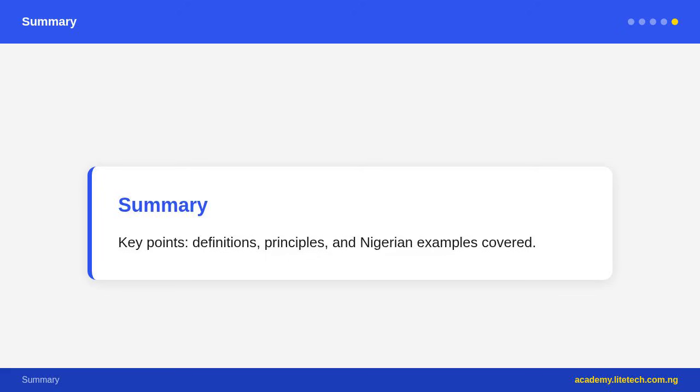The 3 circles: addendum, tip, circle; pitch circle; dedendum, root, circle. Module: the ratio of the pitch circle diameter, in millimeters, to the number of teeth of a gear. It is a measure of the size of the gear teeth. Gears that mesh together must have the same module.